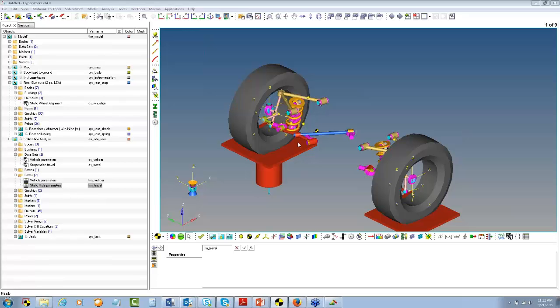All right. So in that condition, I was saying about jounce and rebound bumpers. Suppose you know that your wheel travel, if it is about 2 inches, it is going to hit the chassis. Your wheel is going to hit the chassis. This is generally not the case in a Baja car, because they are open wheel kind of vehicles. However, when you have your general vehicle, in which your wheels are covered, you know that if it goes above 2 inches, it is going to hit the chassis, and that is a very undesirable kind of feeling.